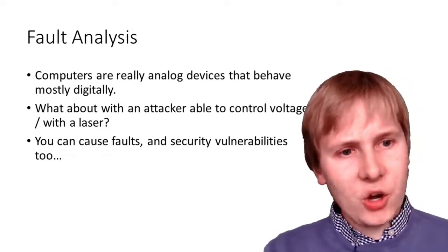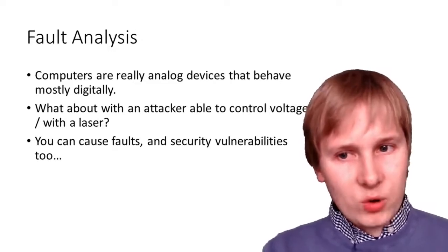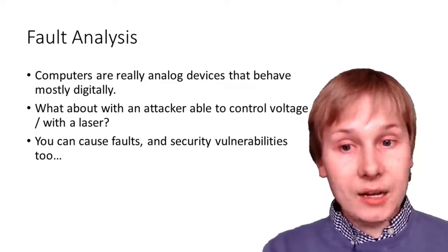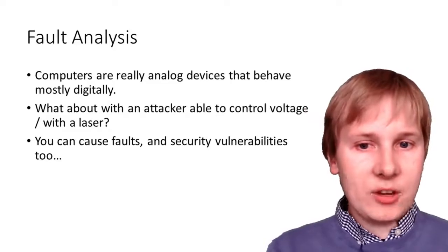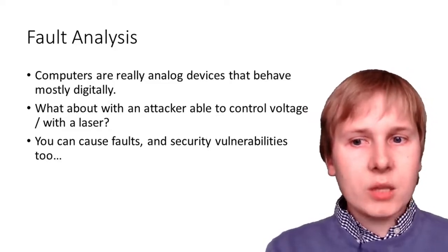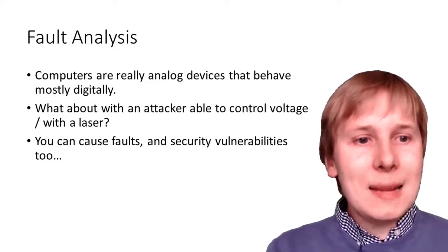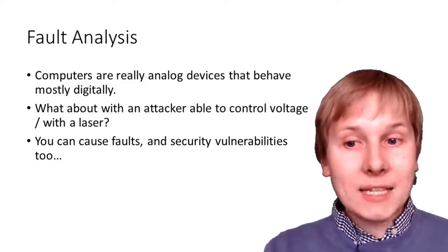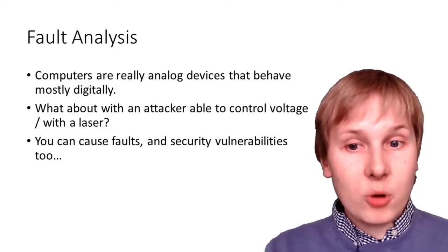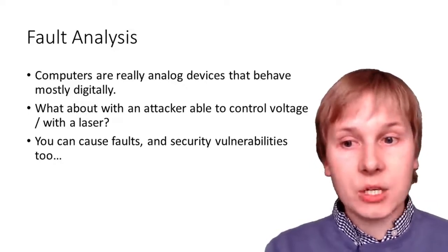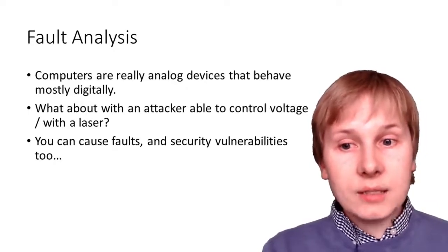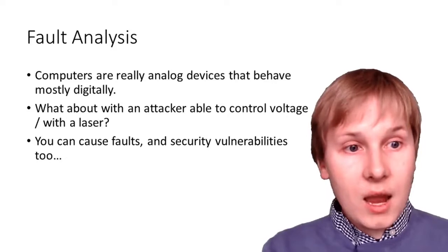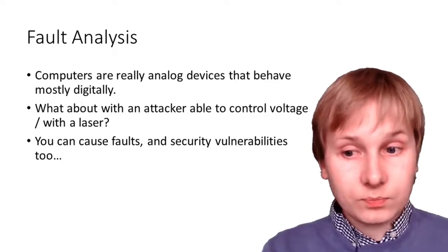But we're interested in security of the device, where it's less random error that we're interested in and more deliberate circumvention. An attacker can deliberately induce the worst case behavior out of our supposedly digital devices. So what if your attacker can deliberately induce flips in transistors by shining laser beams at them, for example, or messing around with the clock frequency input to make the processor work out of its safe range and therefore glitch? They can, and it's a real problem for crypto algorithms which start to leak their secrets once they get their answers wrong via a technique called fault analysis.